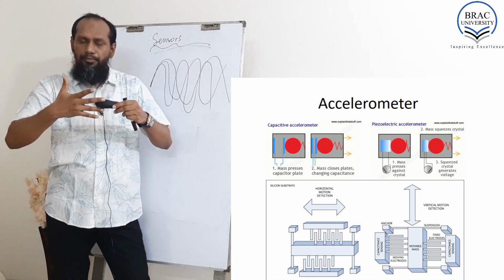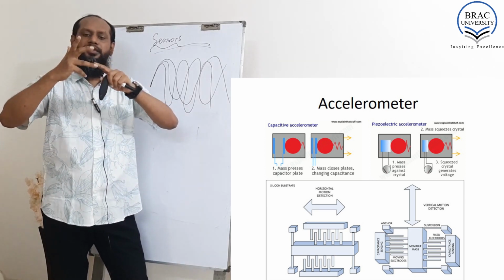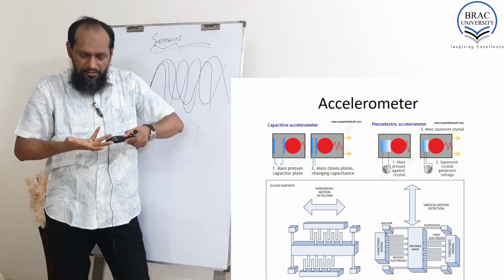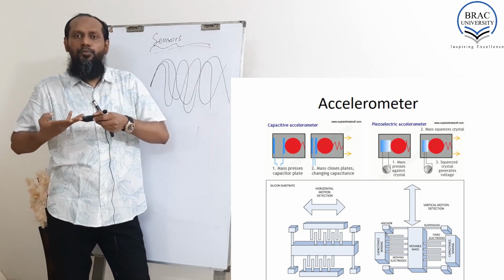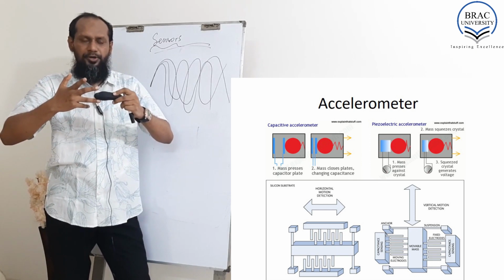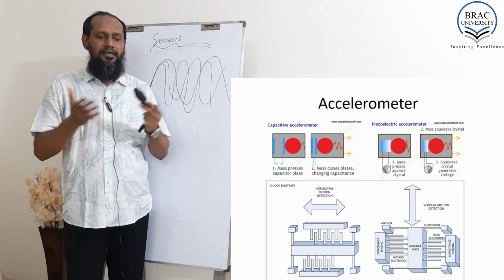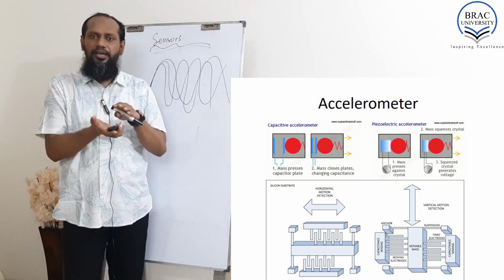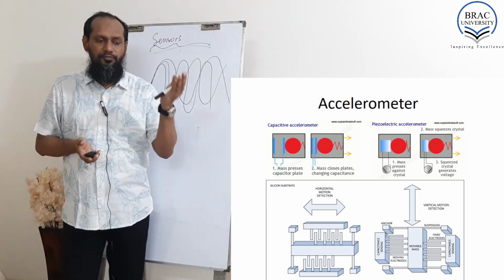Another way is the pressure. Like if we use piezo material here, when more pressure is given to the piezo material, it gives more voltage. But in this position, no pressure. In this position, it will give pressure on this piezo material. So by measuring this, we can measure the tilting, or in which way the thing was tilted. Okay, this is the concept of the accelerometer.